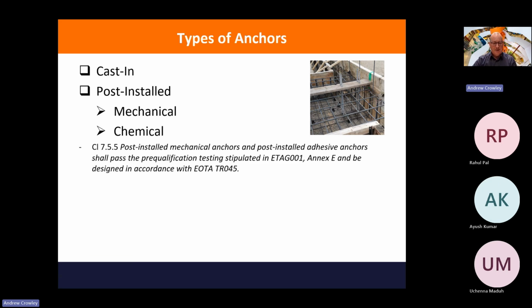And NZS 3101 has a clause that basically says post-installed anchors need to be pre-qualified using the testing stipulated in ETAG 001 and EOTA TR 045.